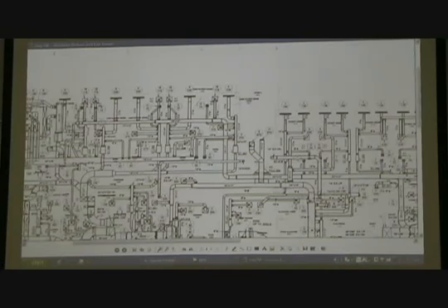This looks like a typical patient room where you've got a slot diffuser along the perimeter, return grill here, supply grill here, another supply over here. Another supply duct going down to another floor. This looks like the return coming from the air handling unit going down another floor, branches off here, probably wraps around the building like this.